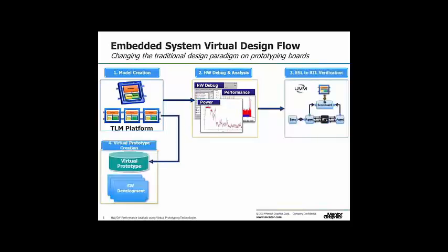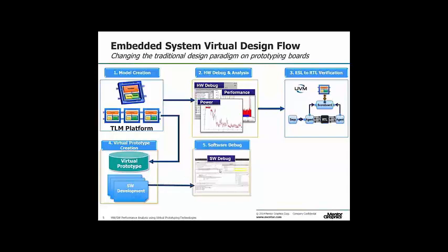Meanwhile, whilst these SystemC models are being created, the RTL verification can start, a UVM test bench framework can be constructed, and the SystemC models can be used as part of this test bench. And then once the platform has been validated, it can be supplied to software development teams to really develop and debug the real-world software upon without having to wait for some real hardware.